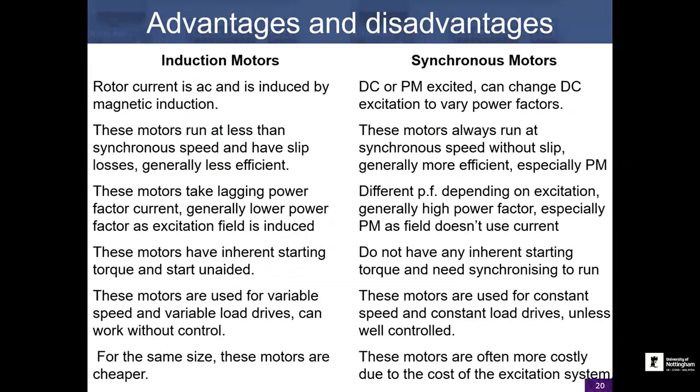Then we highlighted the overall advantages and disadvantages of induction motors. As I said before, you won't be asked to talk directly about synchronous motors, but it might come up that you'll be asked to talk about them with reference to induction motors. So some of the key differences in characteristics are in terms of how they operate by induction versus how they operate by synchronous fields. You might be talking about operating points: induction motors operate at any speed but synchronous. Synchronous machines, as the name implies, always run at synchronous.